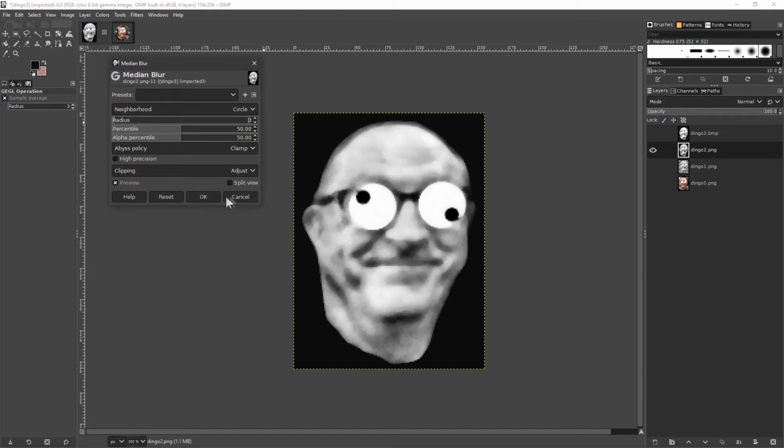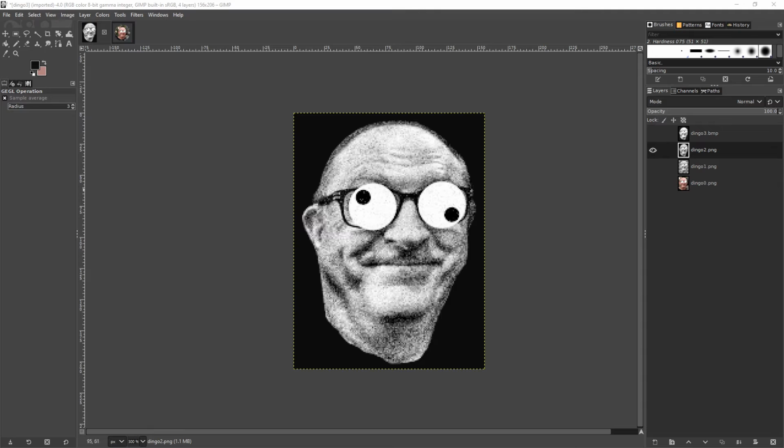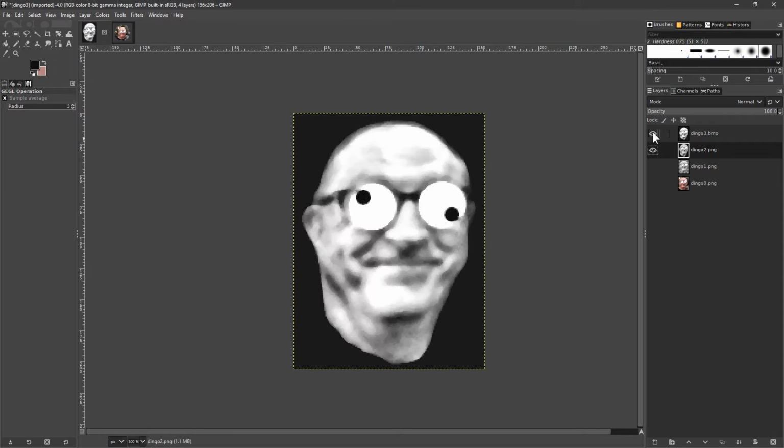And the reason that we apply a blur is that when it is this sharp, it would be a very jagged tool path up and down, as the white pixels are high and the black pixels are low on the contour, and so when it's got a noisy picture, it would be a very noisy tool path, and I wanted a smooth tool path, so I thought I'd apply blur to make it a much smoother outcome, a bit like visual sandpaper.